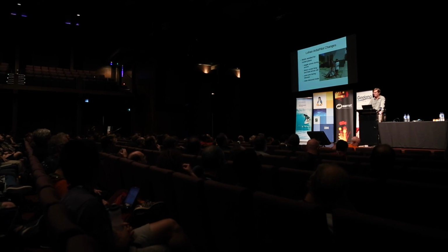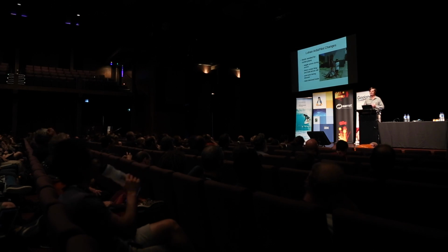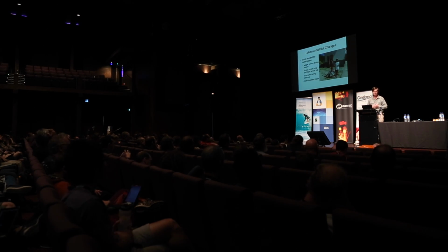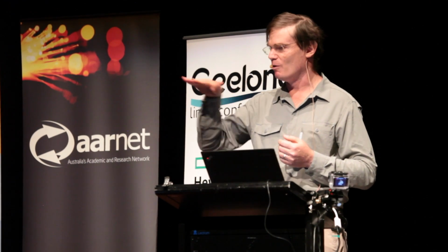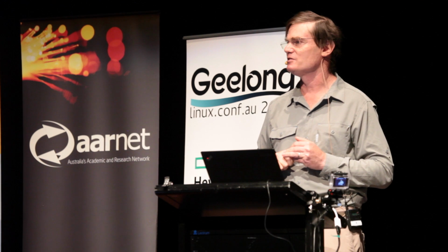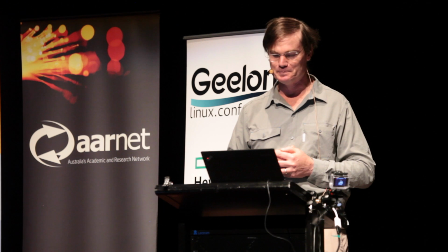There is, however, a slight issue that knowing the altitude to land at is going to be somewhat difficult, because it just has a barometer on board for altitude, and barometers tend to get a little bit upset when you drop them down to minus 50 degrees C and have them going for a couple of hours in a weather balloon. And we're hoping that it will try to land on the runway, but it might decide to land 10 metres under it or 10 metres above it or something, and that could get interesting.